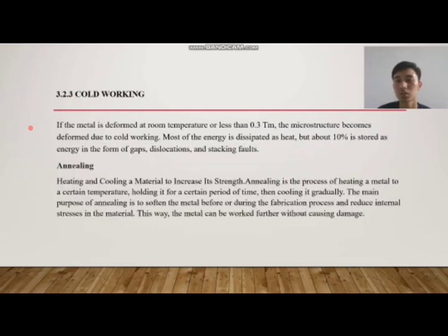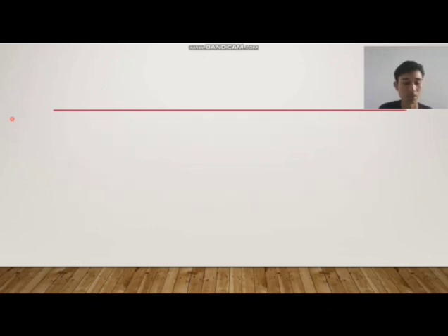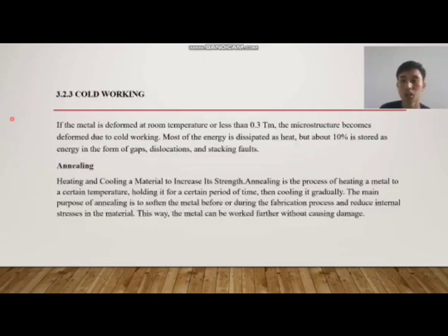Next, 3.2.3 Cold working. If the metal is deformed at room temperature or less than 0.3 Tm, the microstructure becomes deformed due to cold working. Most of the energy is dissipated as heat, but about 10% is stored as energy in the form of vacancies, dislocations, and stacking faults.